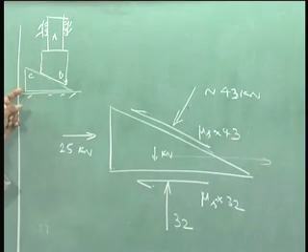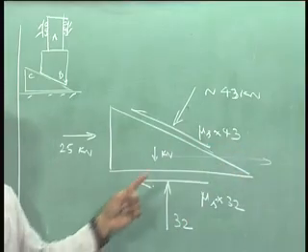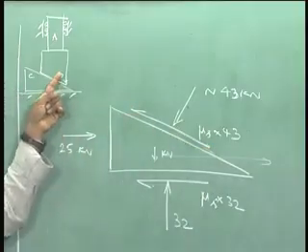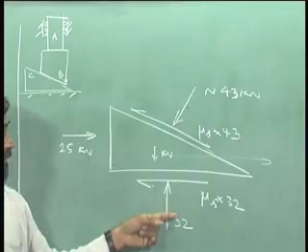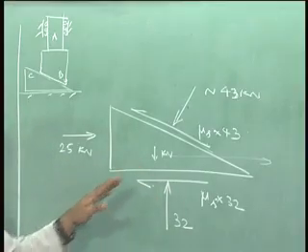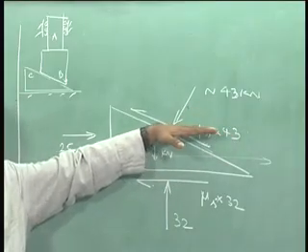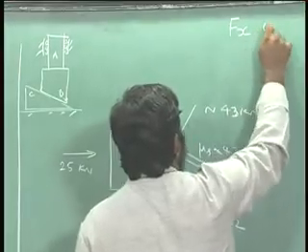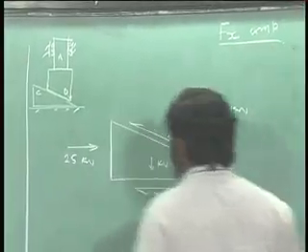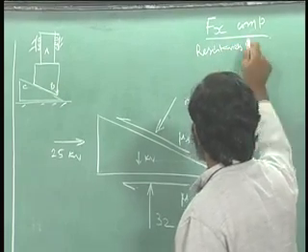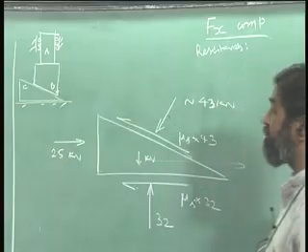Now if this goes towards the right hand direction, the resistance is offered by number 1 the frictional force that is coming on because of BC contact, and the frictional force offered by ground onto this wedge, okay. The other resistance is due to the component of normal reaction, okay. So let us just write those. So I am just going to write Fx components, okay. First let us look at the resistances to this application of force.